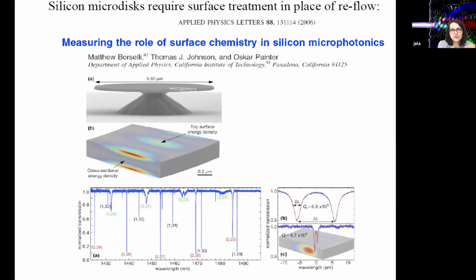Maybe there is some effect of the geometry of the pedestal where this starts kicking in for modes that have n equal to 3. Because remember, modes that have large number n are interacting with the pedestal. That's the problem. So I would assume that the reason you see these low Q modes that are split by a lot has to do with the interaction of the inner ring with the pedestal.